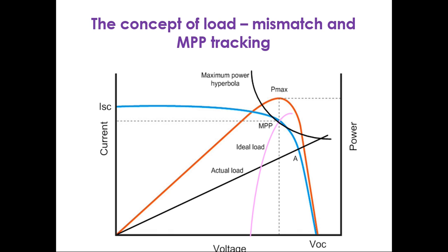If you go back to the fundamentals of the maximum power transfer theorem, covered in the undergraduate electrical engineering program in the network analysis subject, you have the concept of RTH equals RL. At that point the maximum power is transferred from source to load. This concept is used here also, but that concept is for a fixed load. Over here the load is variable in nature, and the source is variable in nature.